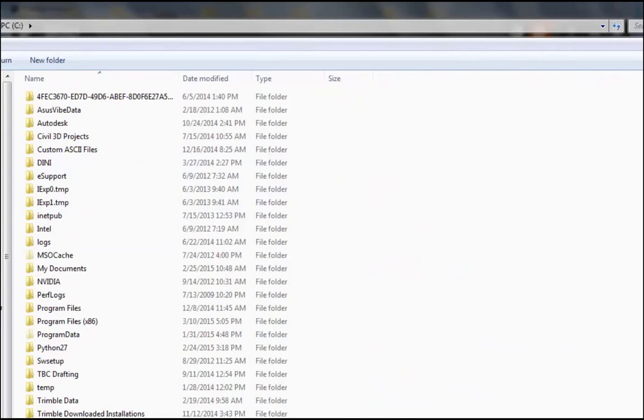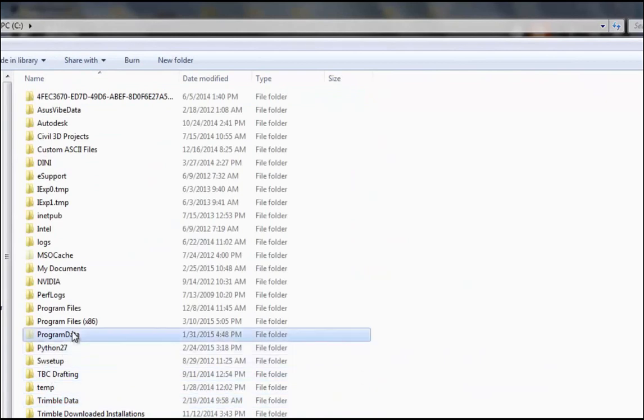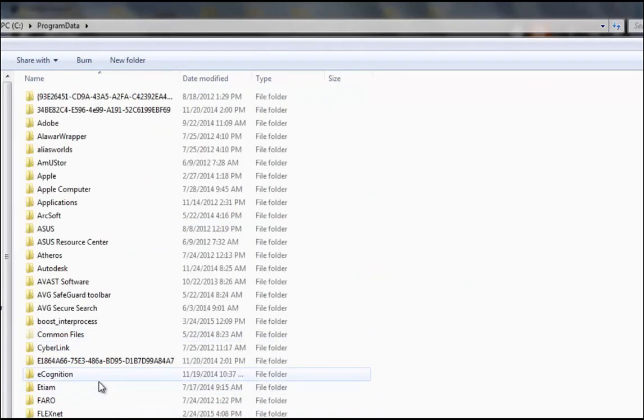Also, what I can do with that TTM file, and maybe it would be more advantageous on the roads side of this, is let's say Brian exports out a corridor for me, and when he exports out a corridor, it's designed to finish surface, right? Well, let's say I need to stake subgrade or whatever. I can still stake this finished grade corridor, centerline, station, and offset, but I can load a TTM surface of subgrade, and I can have it give me my cuts or fill to subgrade, but reference my finished grade for my station and offset, so I have some flexibility there.